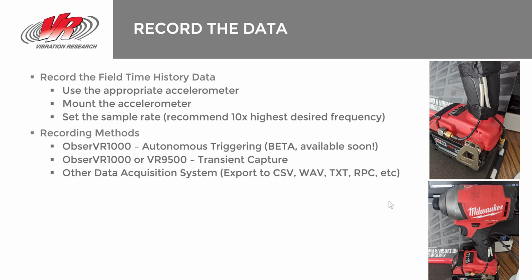And some important considerations to make when mounting accelerometers and even selecting an accelerometer is to have an understanding of the event that you're trying to acquire. So I want to make sure that I have sensors that are capable of measuring the peak accelerations that I expect to see, and that I have them mounted such that I have the ability to appropriately measure the frequency range that I'm looking for.